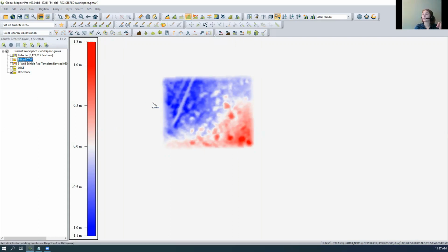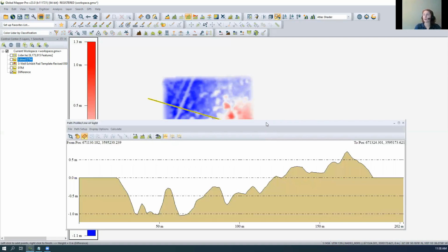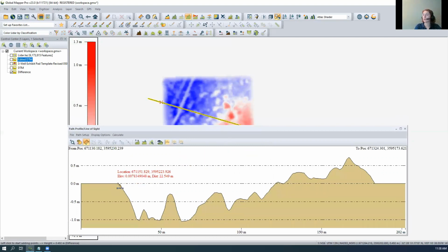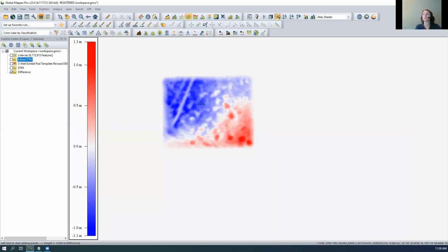Turning off the underlying terrain layers, this is a gridded layer, although not showing terrain or elevation in the classic way. Each pixel does contain an elevation or difference value. And that means we can use the path profile tool to view it. Along this cross section that I drew, we have areas where earth would need to be taken away, and the area from 0 to this surface is the amount at that particular coordinate location. And then areas where earth would need to be added or filled in. So that shows us where those cut and fill volumes that were calculated are going to be distributed, and how they really impact the terrain area. And this is a great visual representation of that predicted change as we go to implement this new project.